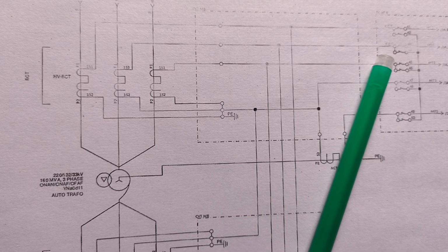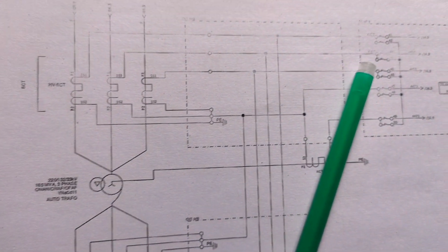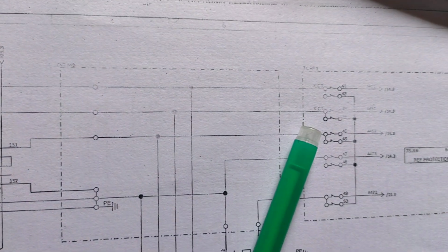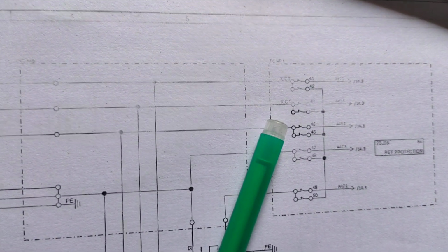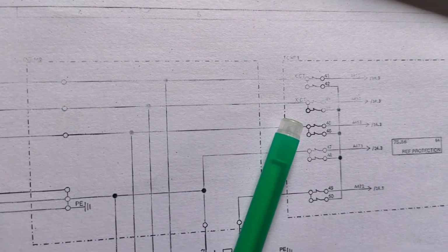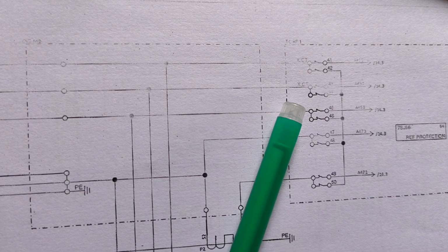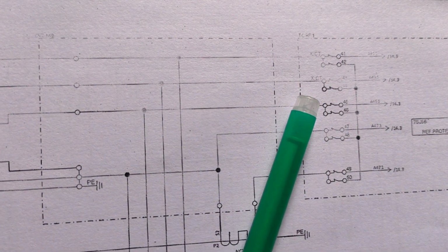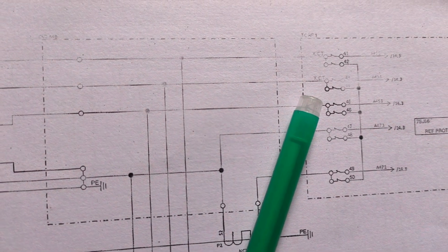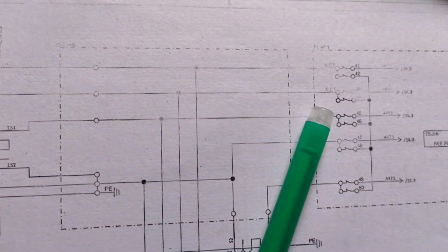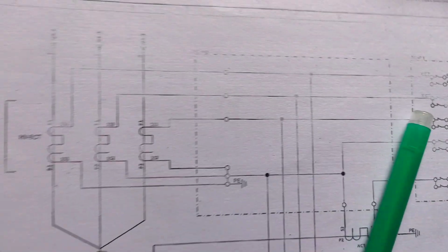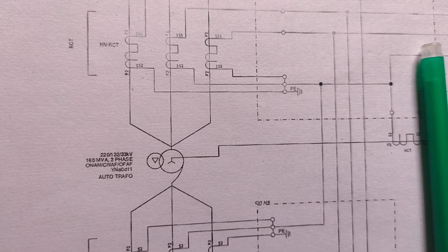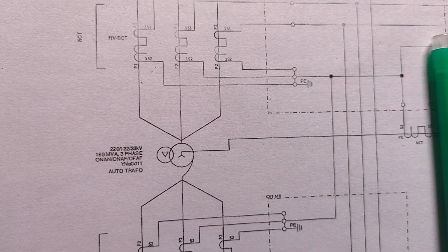When anything bad or any harmful effect occurs, the REF protection relay will instantly operate, and this relay will forward its DC supply through its NO contact mechanism and provide power to the circuit breaker trip coil, and the circuit breaker instantly trips the transformer. Also the HV and LV master trips are connected in parallel with each other. If the primary side, that means the HV side master trip, has operated, then instantly the LV side master trip will operate accordingly. So the faulted sections of the transformer are isolated from the live parts, and the materials and costly equipment are saved from big property loss.